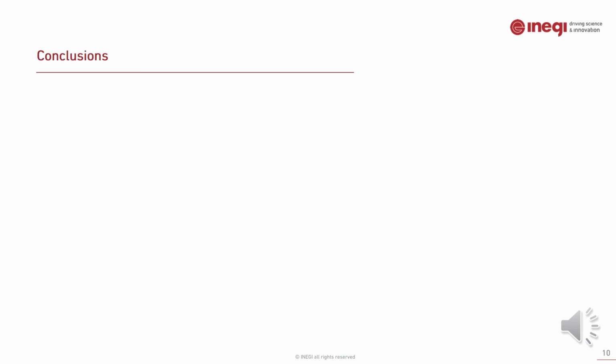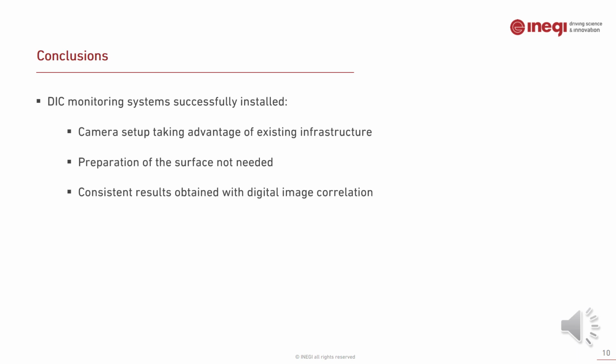There are now some conclusions we can take. We have installed monitoring systems based on digital image correlation with a camera setup taking advantage of existing infrastructure without the need for the preparation of the surface with a speckle pattern, and the results obtained were consistent.